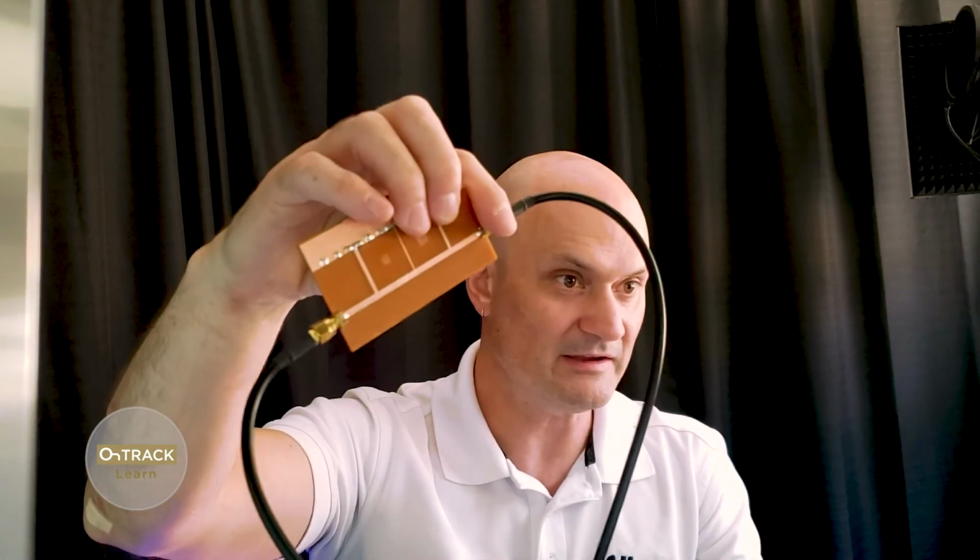And it gives you the transmission line segment lengths that you need to calculate things like this filter here. This was done actually using that tool, and it's free. And of course, you jump into Altium Designer and build your filter components and lay it all out on a board and make it up, and it works brilliantly.